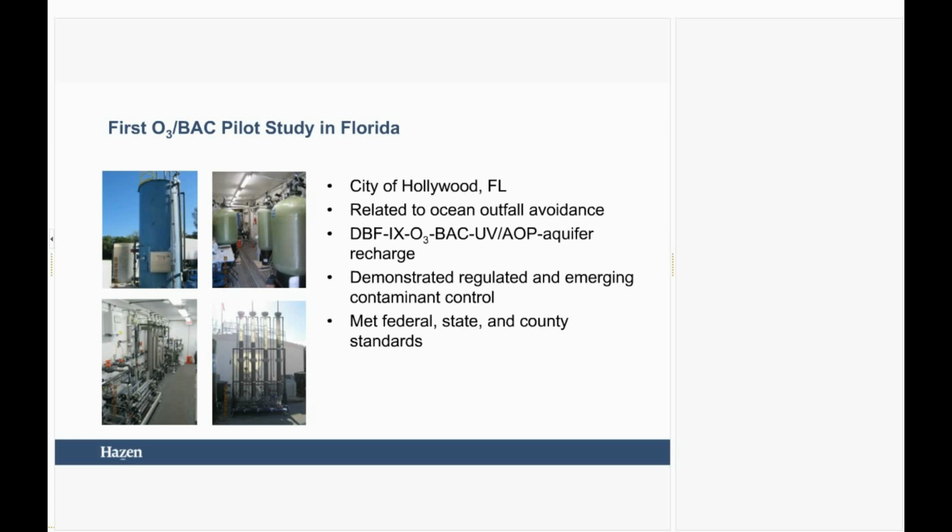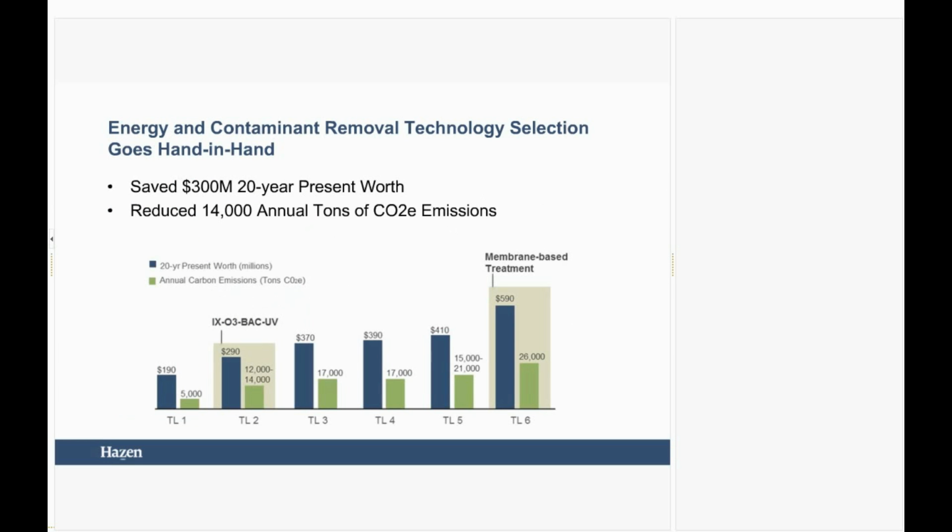osmosis system. Important to point out that the water was recharged into the Floridan aquifer, which is an aquifer that is moderately saline and so requires treatment on the way out. So the system was operated in that fashion such that RO wasn't used twice in a sense. And from an energy standpoint, you can see here that using that treatment process had some specific benefits and energy savings.